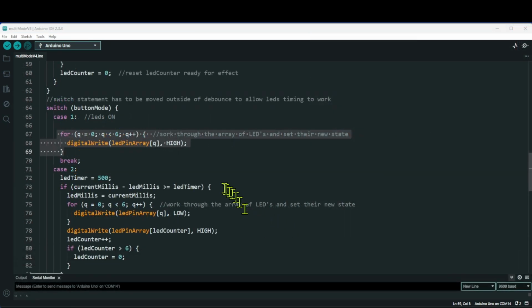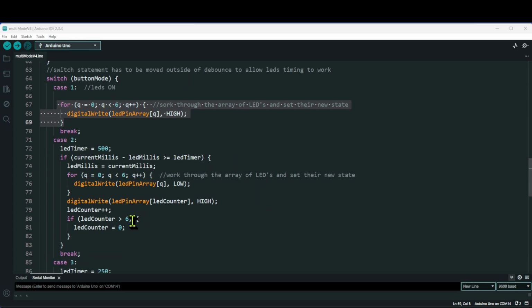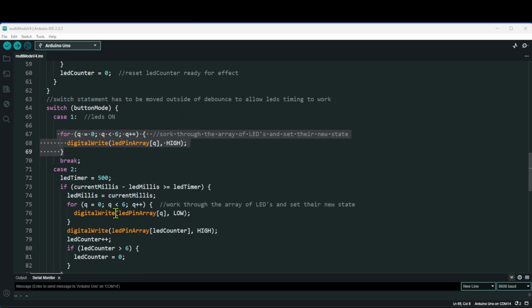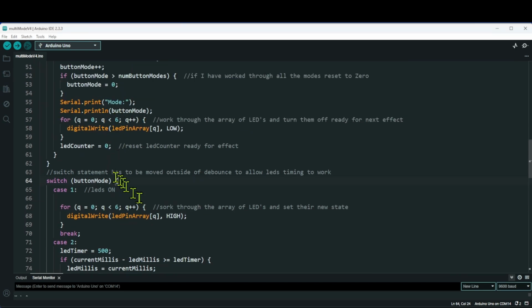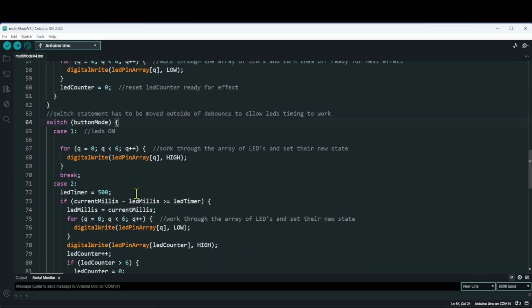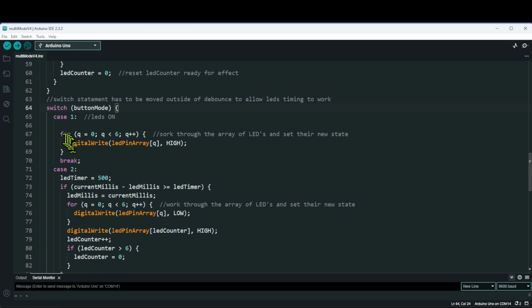Now, the important part about today's lesson is not the different ways of flashing 6 LEDs on and off. What I want you to try and grasp is how you can use a single button to change the mode to do different things with the same Arduino without having to upload a different sketch. So we could press for mode 1 and it might take a temperature reading.